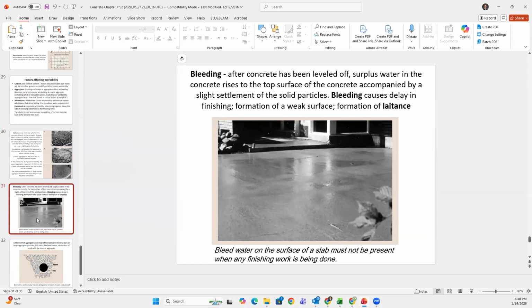Let's say you use the material in the middle and you did a concrete pour. Towards the end, in the last hour or half hour, you should not see shine, water coming to the surface like that. A good concrete, when it's done, is not cured, but doesn't have water or shine on top. This is an indication that there was a little too much water in here.